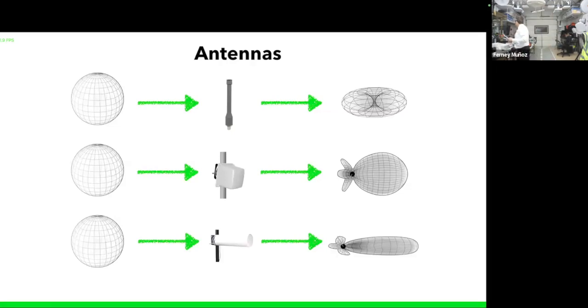This AP is an omnidirectional access point. If I mount it like this, it's like a donut. See one on top? It covers 360 degrees around it. And then the energy, as you can see, is weak in here. And sometimes they say, my Wi-Fi is really low. I don't know why, because I'm right under the access point. Maybe you are in the hole of the donut. And then over there, the signal is not very good, because this guy can have a pattern kind of like this. Okay? Omnidirectional in the horizontal plane.